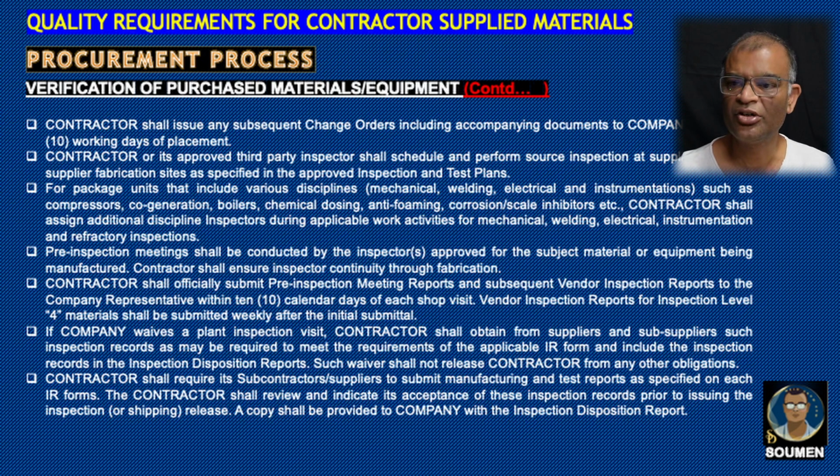Pre-inspection meetings shall be conducted by the inspector approved for the subject material or equipment being manufactured. Contractors shall ensure inspector continuity through fabrication. Contractors shall officially submit pre-inspection meeting reports and subsequent vendor inspection reports to the company representative within 10 calendar days of each shop visit.